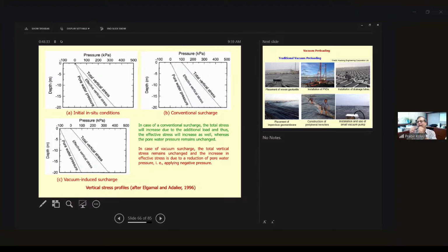Water pressure will try to separate these particles. So basically, instead of friction or increasing the strain, it separates the particles, and suddenly the soil loses its strength. That's why during an earthquake the pore pressure increases. Suddenly the soil loses its strength because there is no contact between the soil particles, and then the soil or foundation collapses.